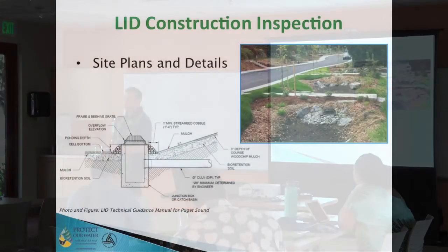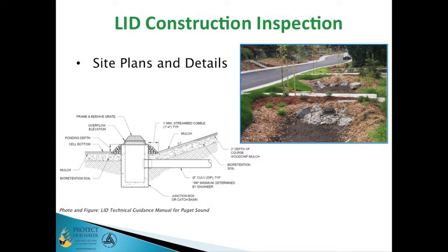Same with your plans and details. Again, you're all used to looking at plans for projects you work on all the time. When we start looking at LID features, some of the gradings and the slopes and the inlet elevations can be critical on how these things function.